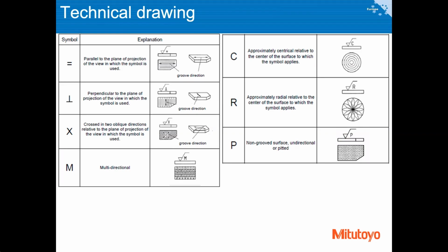If you have certain areas which look very smooth, and on the same surface some areas which are not very smooth, you need to measure the worst area to check if it suits your requirements, so that the good one will definitely suit. These are two recommendations, but sometimes people don't follow them.